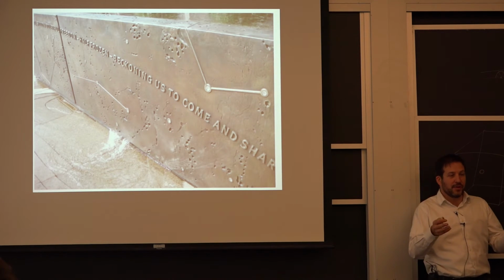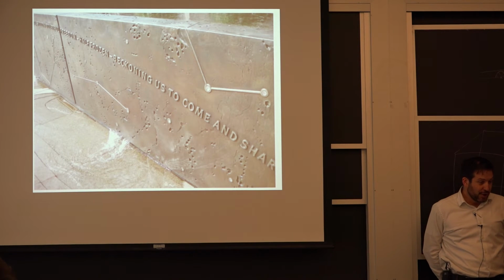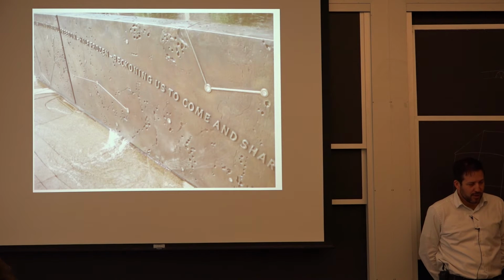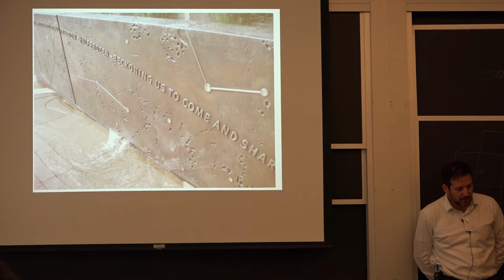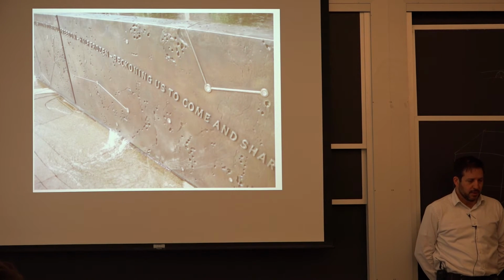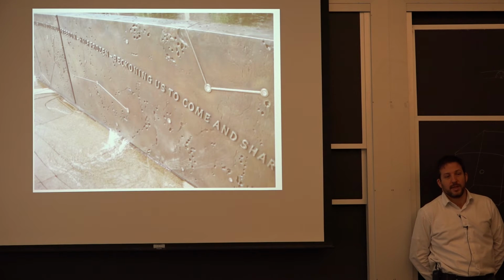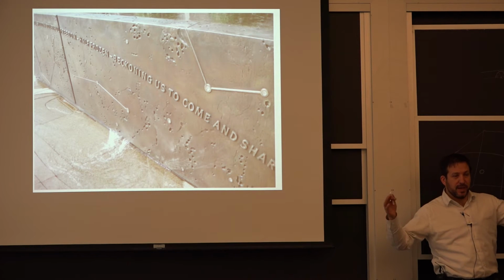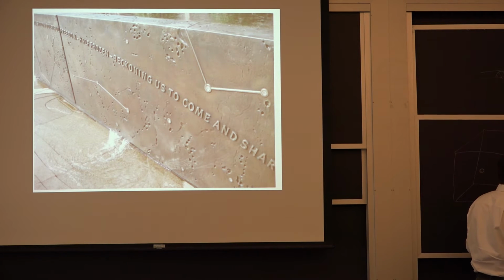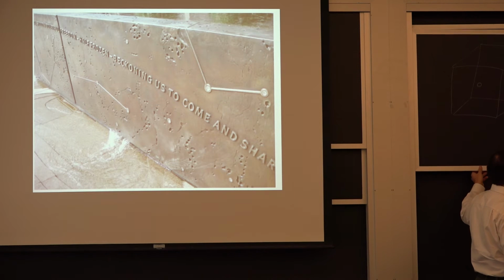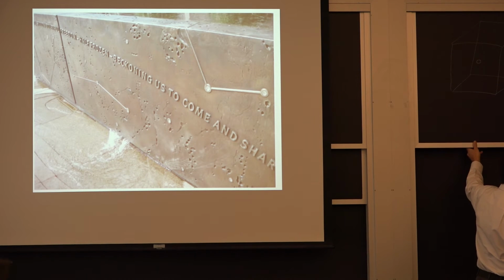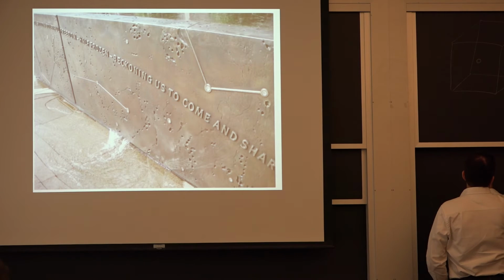So the artist here was in charge, if you will, of the project. One of the major issues that happened there is nobody really thought what is going to happen between the summer and the winter. So if you have this big tunnel that's 60 foot long, just a little bit like when we were talking about the plastic pipe, it wants to expand and contract.